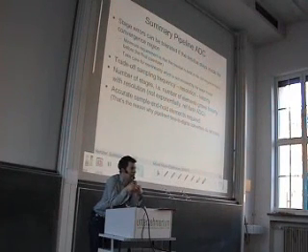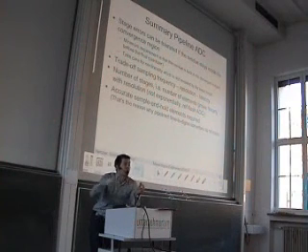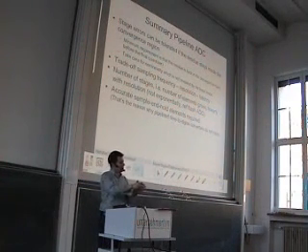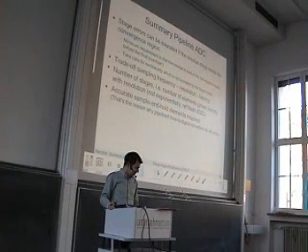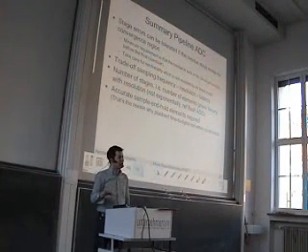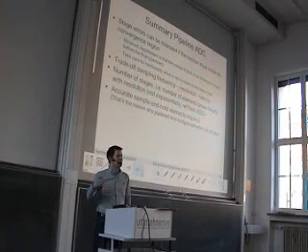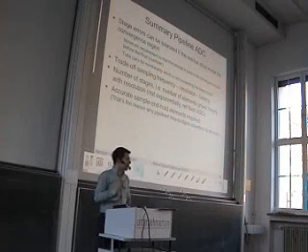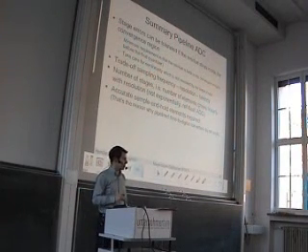The pipeline ADC is more or less the same as a successive approximation algorithm, which is unrolled. So it does not run in a loop, but it runs through a sequence of n times the same block. We can see here that the number of blocks increases linearly with the resolution. So if we want additional bits, then we need additional stages. It does not grow exponentially, and this is a big advantage.